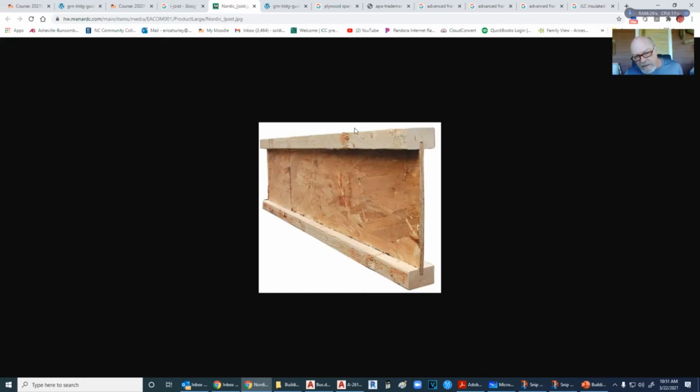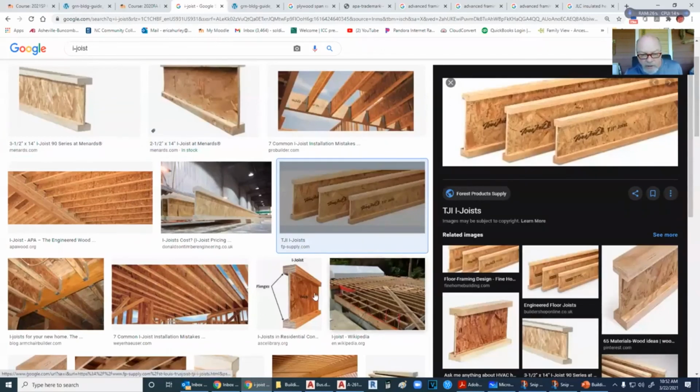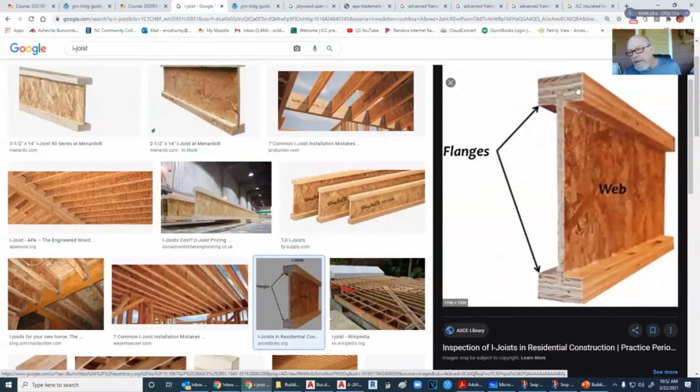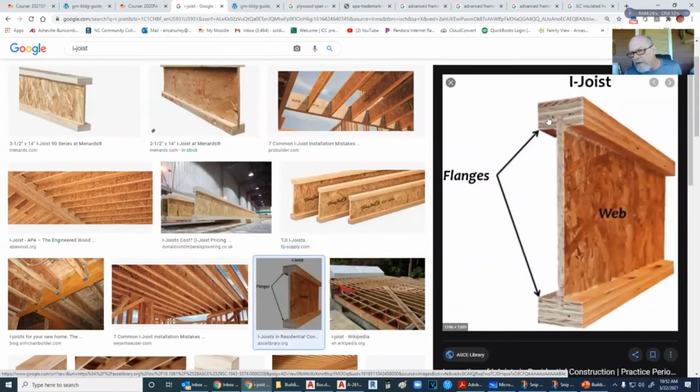And here's that finger joint that Danny's talking about on this one. So we can make these as long as we need to. However, because of these finger joints, these can actually add a weak point in it. So we switched over to LVLs. Even though this is laying down, it really doesn't add a whole lot of structure to it, but we don't have a particular weak point in it. We can stop this layer here, this layer here, this layer here, and we can end up with a continuous strong flange on this thing that has no particular one weak point on it.